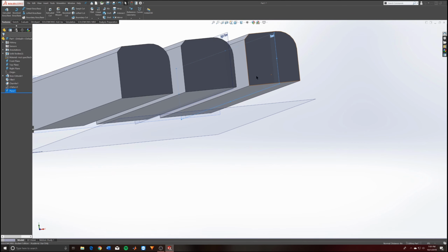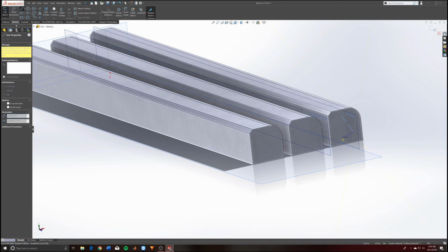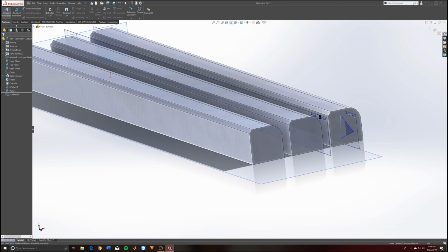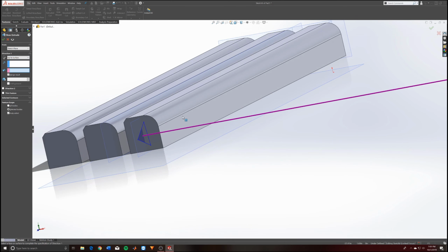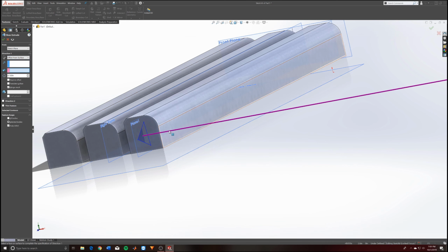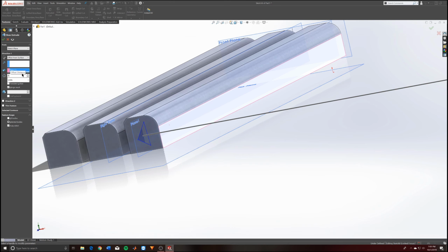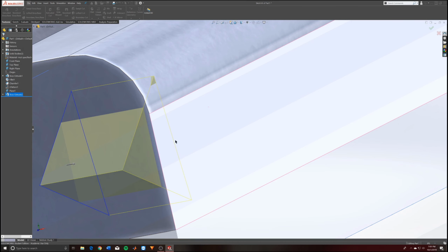And then now I can start a drawing right on that plane, as you can see. This is not how you're going to want to do it, by the way, but I'm just demonstrating something real quick. But from here, this is where you would want to be using these features where you say up to surface or offset from surface. And you click a surface and then you say within 0.1. And as you can see, it's within 0.1 inches of that surface.